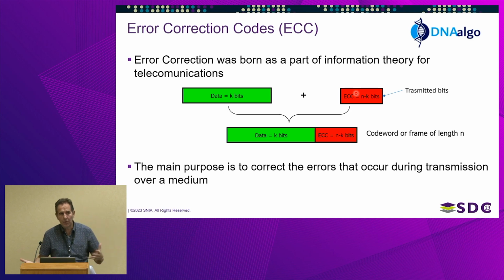So a very simple code could be a checksum. Then the receiver applies the mathematical calculation and says, hey, there's an error in this frame that came. So you have a frame which is made up of the payload plus error correction, and in other applications you could have headers and footers and tail, all that stuff. But in a very simple sense, you have a payload and then error correction bits. That's a frame.